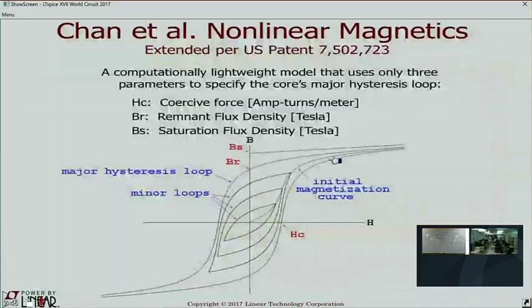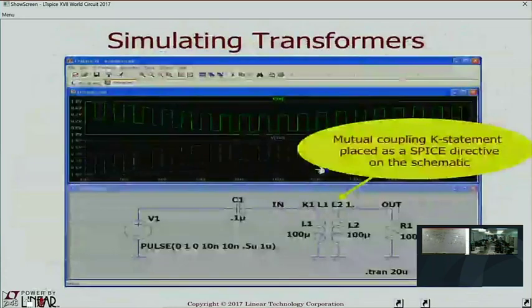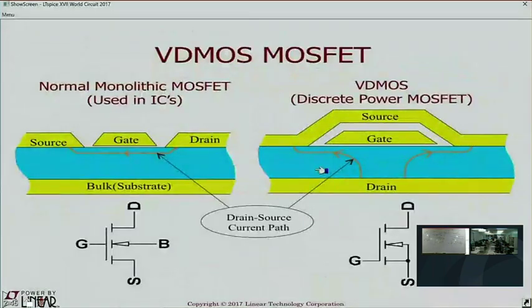Okay. What I want to talk about now is models. First, I'm going to cover how to use third-party models in LTSpice. There's basically three possibilities. It's either a power MOSFET model, or the model is done as a native circuit element, or the model is implemented with a sub-circuit. There are three different methods used.